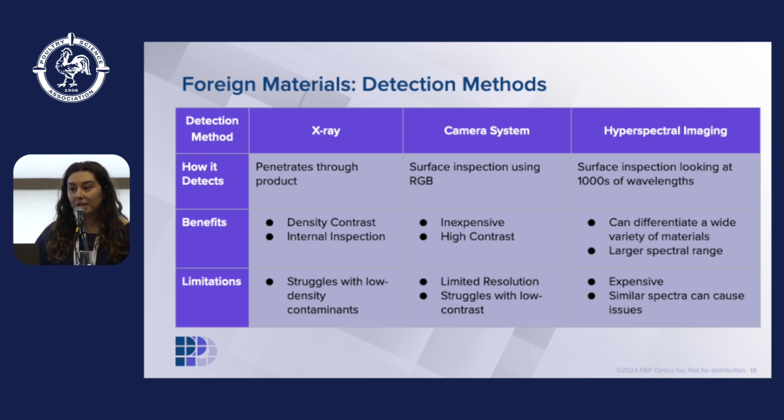Where there are limitations in this technology is low density materials, which do appear in manufacturing facilities. That includes your liners, sometimes cotton, cardboard, those kinds of materials this system will not be able to detect. Lower density plastics have a lower atomic number and density, allowing X-rays to pass through them more easily, but it can result in lower contrast and reduced visibility for the X-ray to distinguish.